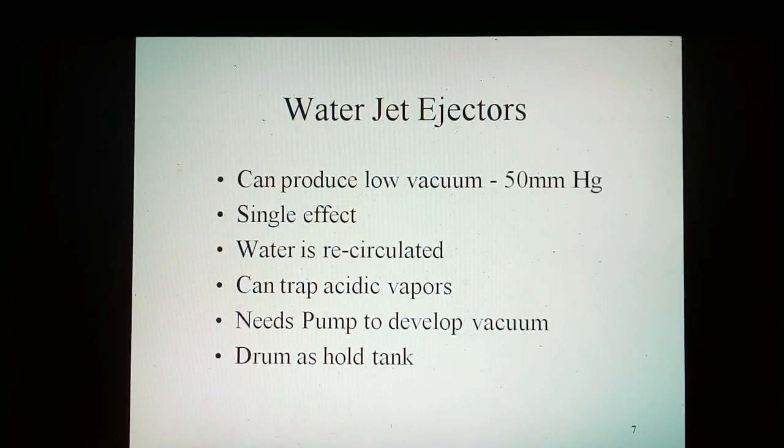Water jet ejector. Pressurized motive fluid other than steam, such as ethylene glycol, alkaline solutions or water, follows the same operating principles as steam ejectors. The system consists of a closed-circuit recirculation system for the driving fluid. The vacuum produced is lower, in this case 50 mm Hg. It can be used as a fitted gas scrubber.